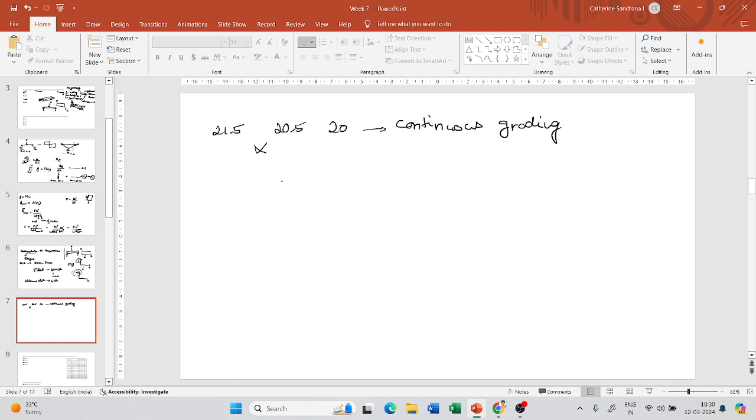So the intermediate PG grade of bitumen should be any of these following numbers, any of these temperatures. Now if you see, these values are at intervals of 3. So these temperatures are also at intervals of 3.